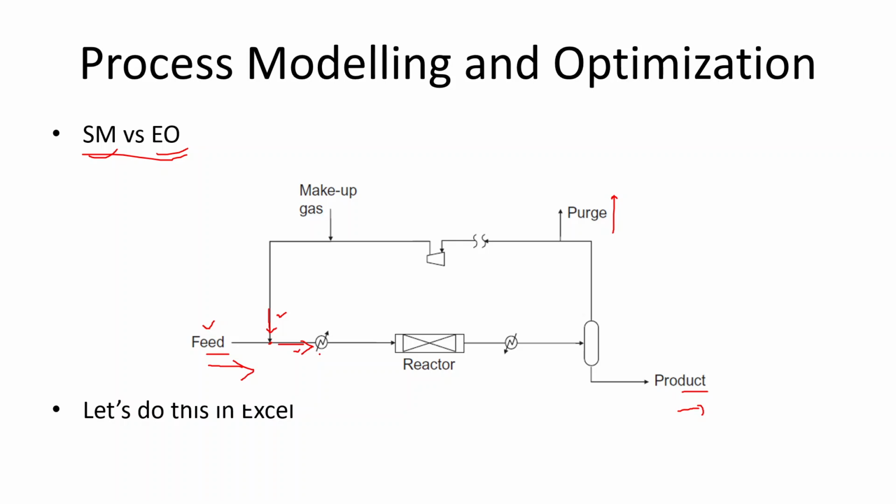Okay, and it goes here in this exchanger, and then if we put in the information related to the performance of the exchanger, for example the pressure drop, and then the required duty or the outlet temperature or delta T, then this stream will be calculated. So we know this, we assume this, and then this is going to be calculated. Then we input information on the block, and this outlet stream will be calculated. So it will calculate block by block.